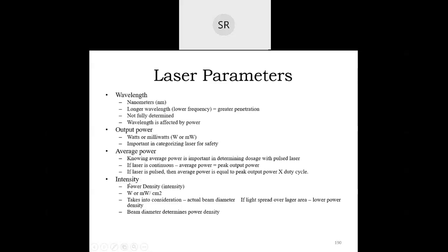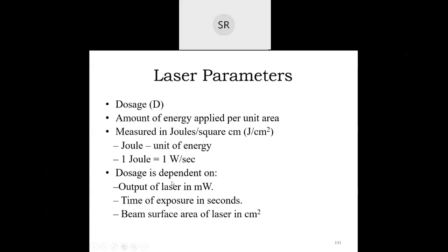So that's why we say it's about the light, whether it is a laser diode or an LED we are using. According to that, it emits the light, and we should know the beam area for this particular light. Generally we say it is a narrow beam and the light is a coherent one. So that's why we are getting a narrow beam, high intensity light.